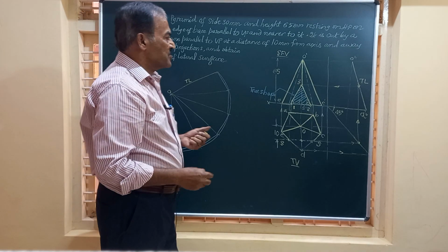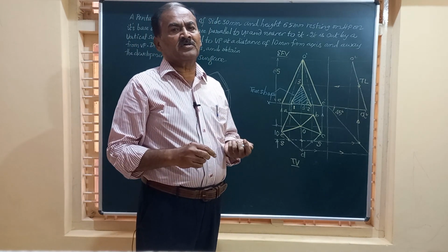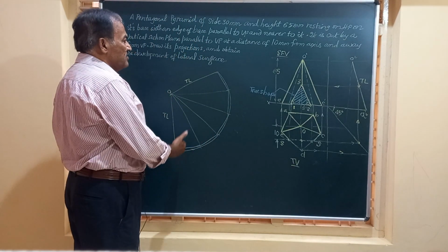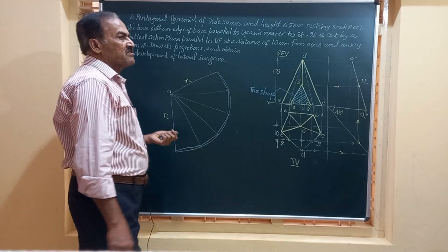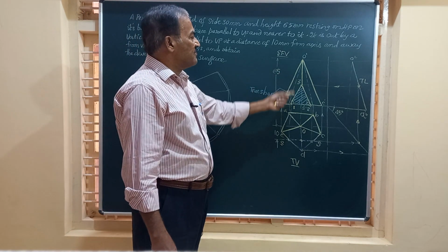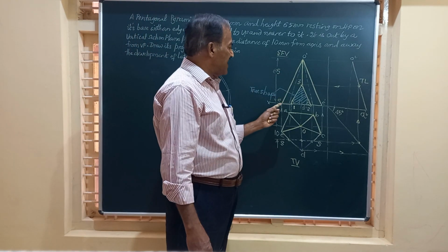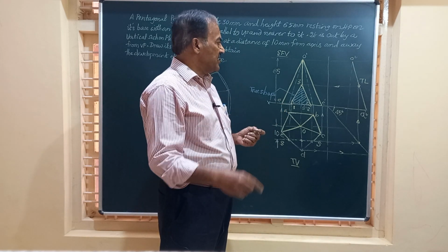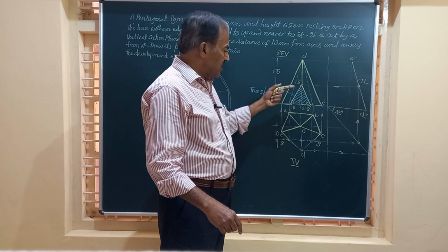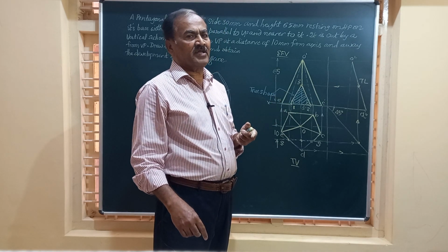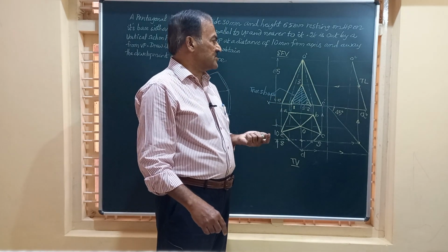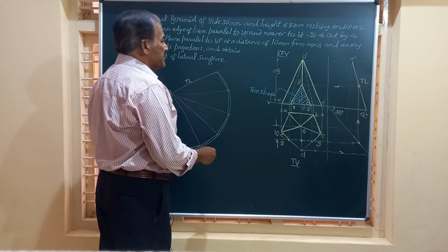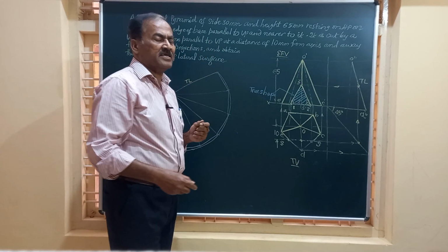Now friends, to obtain the development of the pentagonal pyramid, we have to see from where we should start the development. Here, as you see in the figure, there are 5 slant edges, OA, OB, OC, OD and OE, and none of them is totally removed by the section plane. In other words, you have the provision to commence the development from any one of these slant edges.